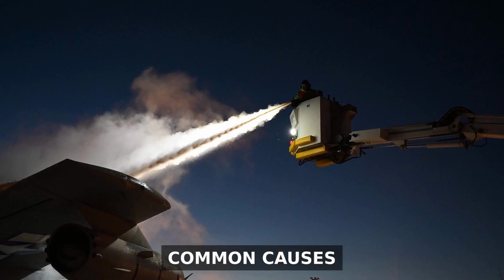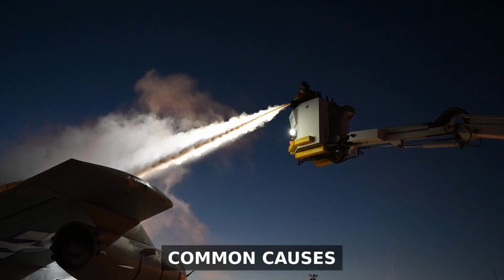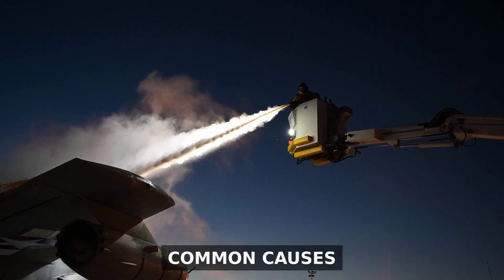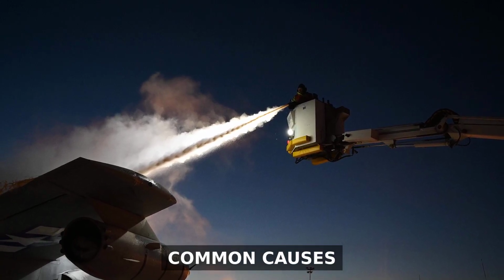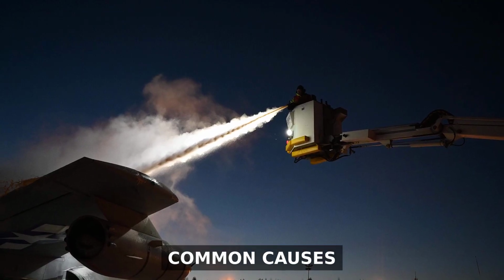Stalls and spins usually happen because of distraction, low airspeed in the traffic pattern, steep turns at low altitude, or abrupt control inputs. Icing can raise the stall speed dramatically. The common thread: the pilot lost track of angle of attack.